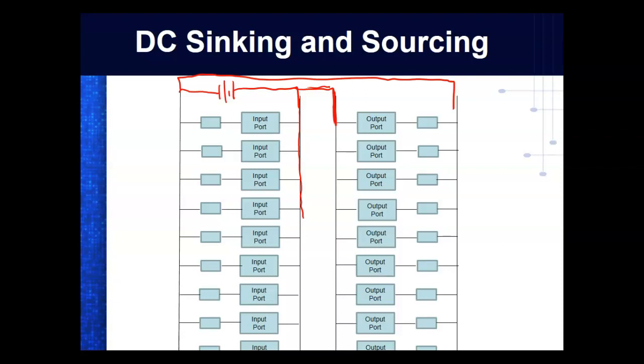So you're right. We have one battery. I have one power supply. And even though the trainer gives you this in the technical manual, the actual PLC has a power supply built into it. If you look at the right-hand side, you'll see it's got plus and minus. But it doesn't supply a lot of power. So if you run push buttons, it will not run outputs. It tells you that in the book. Not in the book, in the technical manual.